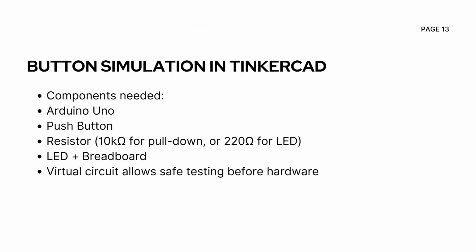Button simulation in Tinkercad. In Tinkercad, we connect a push button, a 10K resistor as pull down, and an LED with a 220 ohm resistor. The breadboard helps us organize these connections.